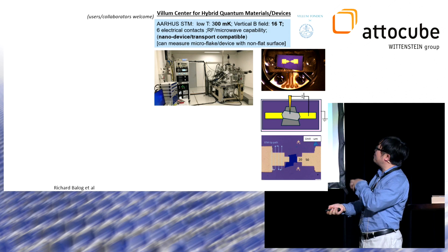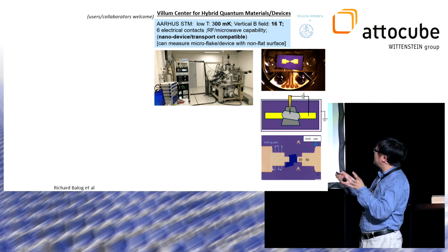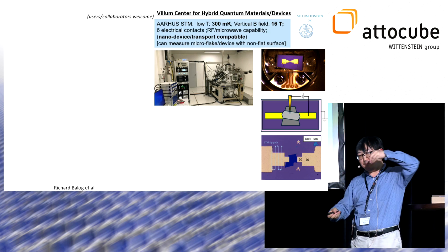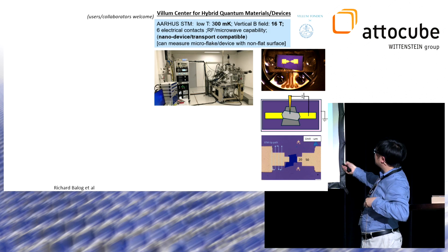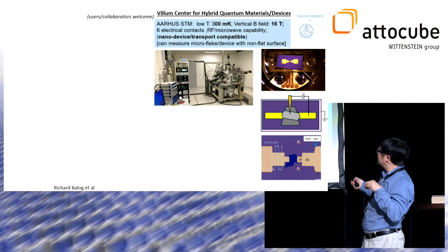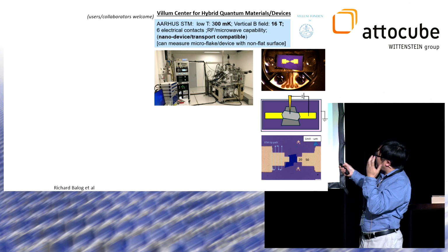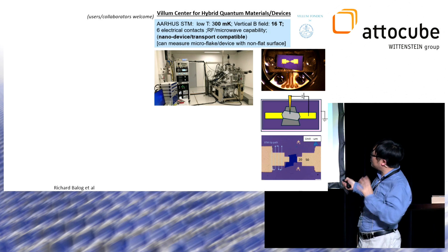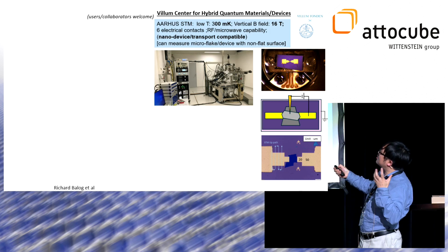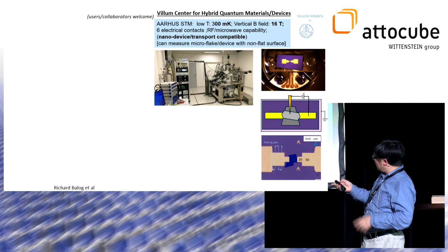Usually, these flakes are sitting on a silicon oxide wafer, and if you don't really approach the tip carefully, you'll crash the tip, right? So you have to develop some methodology, for example, doing far-distance capacitance search to guide the tip, using these lithography patterns as a tip guide to walk the tip to a 2D material. Now we can routinely find these various flakes and perform these scanning probe measurements, really as a nanoscale transport device. We want to look at devices.